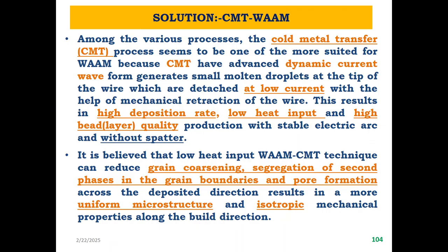the additive manufacturing process. It is believed that the low heat input CMT technique can reduce grain coarsening, segregation of second phase in the grain boundaries, and pore formation across the deposition direction, resulting in a more uniform microstructure and isotropic mechanical properties along the build direction.